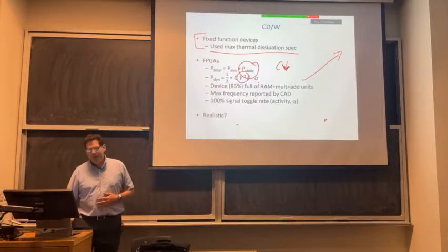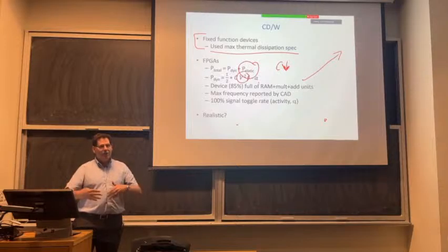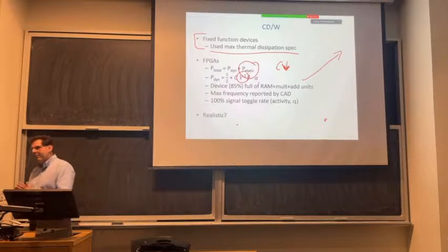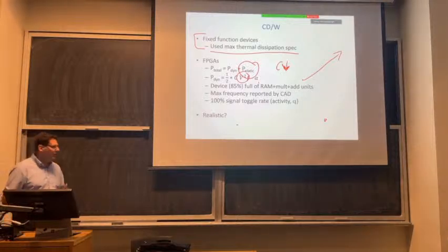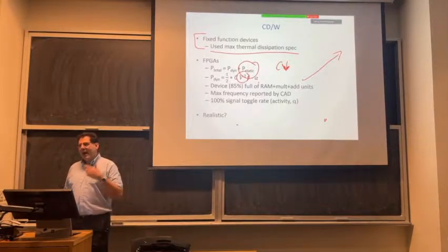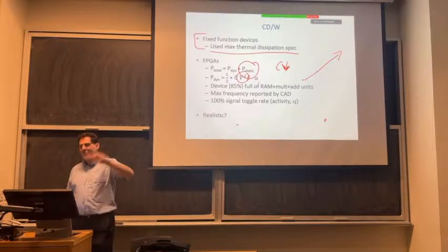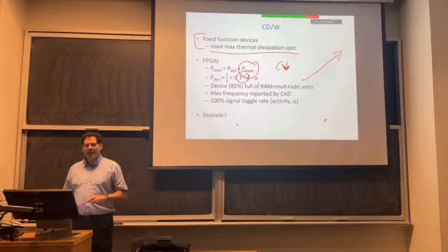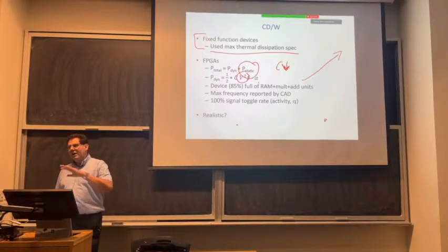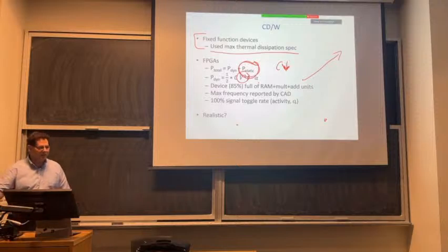But that didn't happen. What actually happens is static power, transistors are getting leakier. Okay, the natural processing of them as they shrink and we drop the threshold voltages, they do leak more. But basically, process engineers and chip architects have to take mitigation measures to bring the leakage back under control every generation. If they just took the previous design and scaled it naively, static power would get out of control. They don't do that. Okay, they will basically do a variety of circuit and architecture tweaks until the static power basically doesn't change. From one generation to the next, it's about the same.